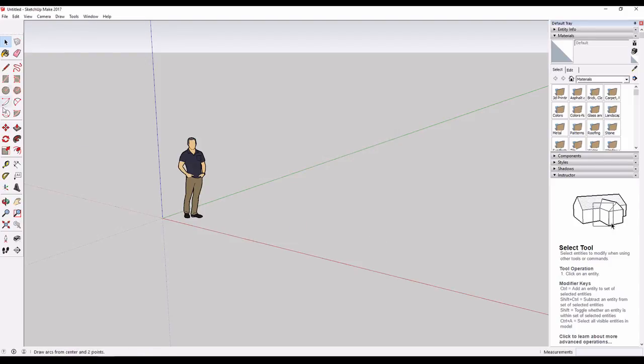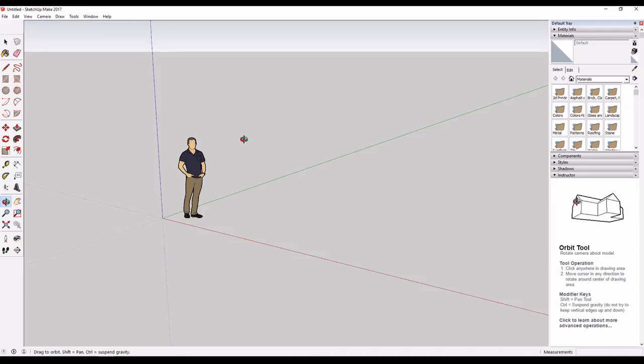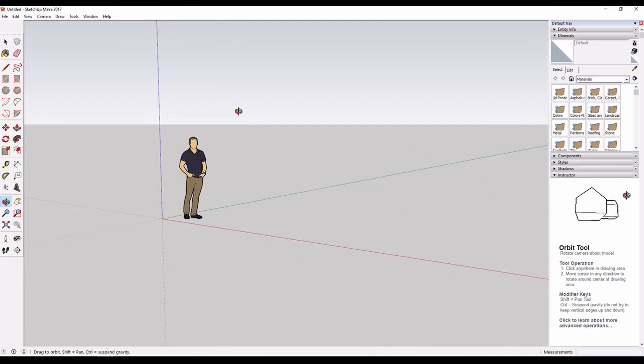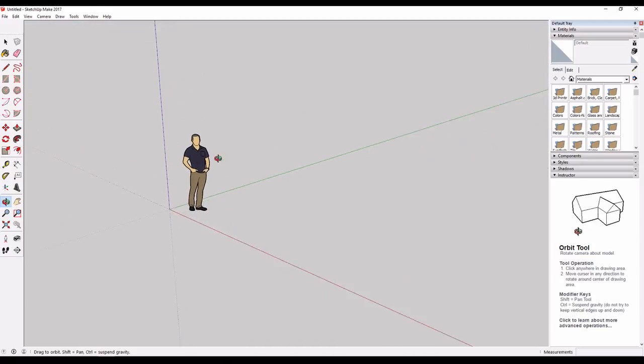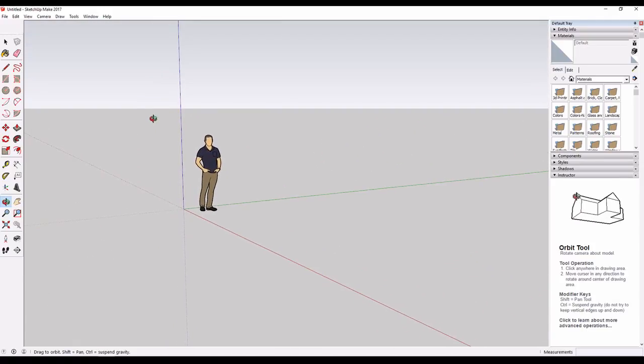When working in a 3D environment, we are working with 3 axes, and having a 3-button mouse will assist in how you create and navigate in this complex environment. Now that you are in SketchUp, try to click and hold your middle mouse button, the scroll wheel, while dragging left and right. This will momentarily enable the Orbit tool and will let us see all around our model.